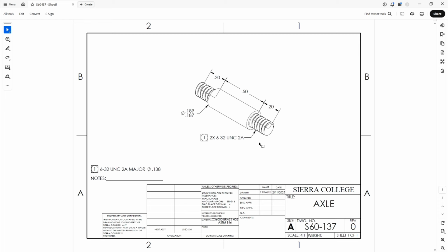All right, let's start with modeling our shape. Now, to use the thread command where you see the threads modeled, you have to actually model a boss feature before you apply the thread that's at the major diameter you need. So that's why we need this 138. The other option is called the stud command. We will use it, but it doesn't actually require geometry to be there. And it'll create a cosmetic stud on a placed location similar to a hole, but in inverse. Okay, so here we go. Let's go to SolidWorks.